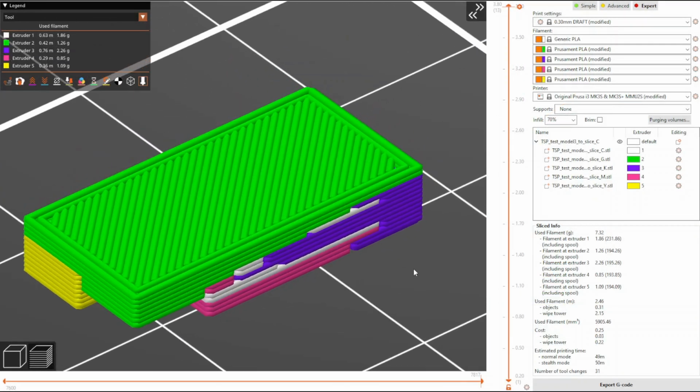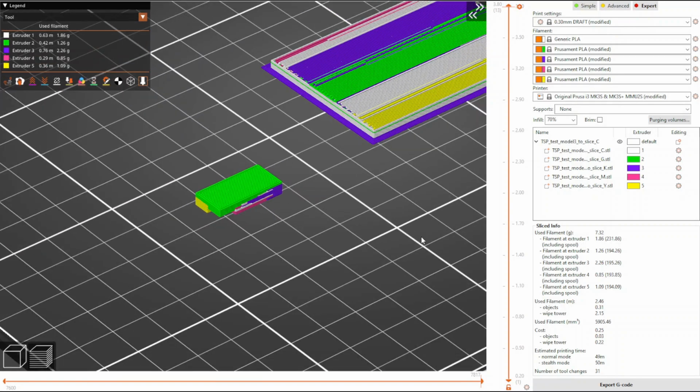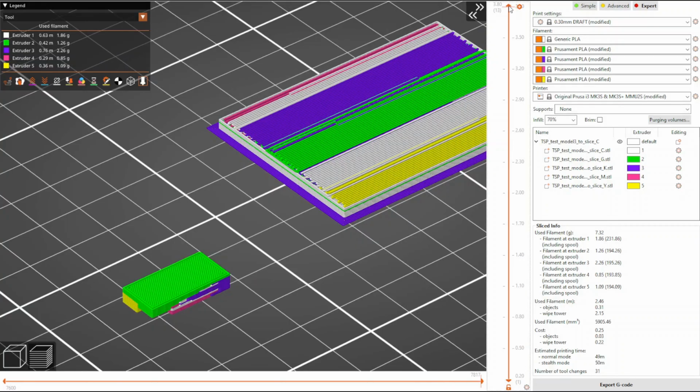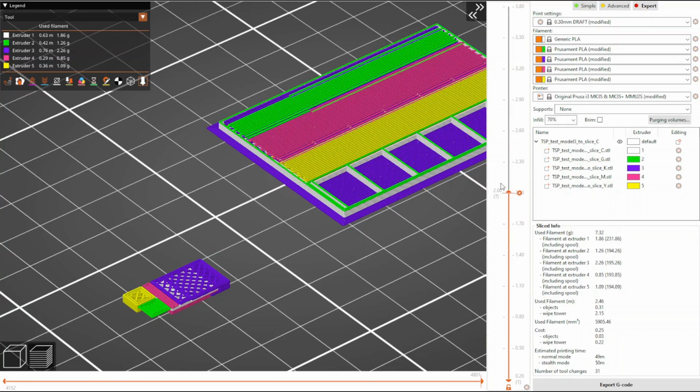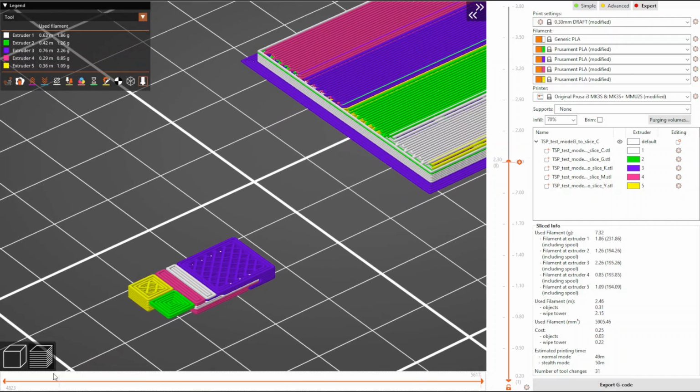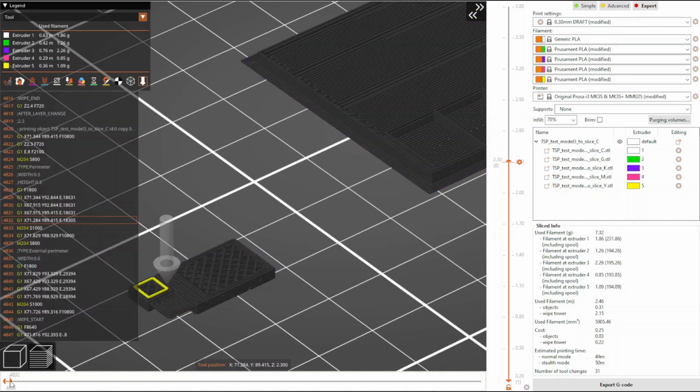Those familiar with multicolor 3D printing know that a significant portion of fabrication time is consumed by forming the wipe tower. This is due to the frequent material changes within almost every single layer, and the physical limitations of using a single extrusion tool, the nozzle.